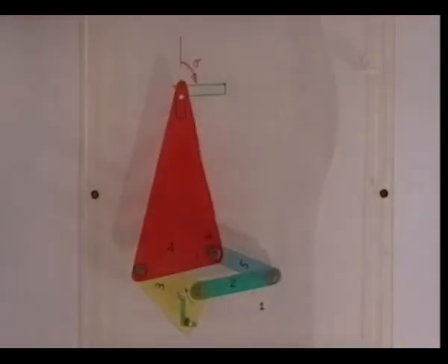As a second example of this kinematic analysis through the link vectors, let us look at the model of this mechanism, which is a copying mechanism or pantograph. What we see here is that this is a 5 link mechanism, the fixed link, and there are 4 moving links, 2, 3, 4 and 5. And the dimensions of these links are such that this forms a parallelogram. This link length is equal to this link length is equal to this. And these two triangles are similar triangles, that is, this angle is the same as this angle and this angle is also the same as this angle.